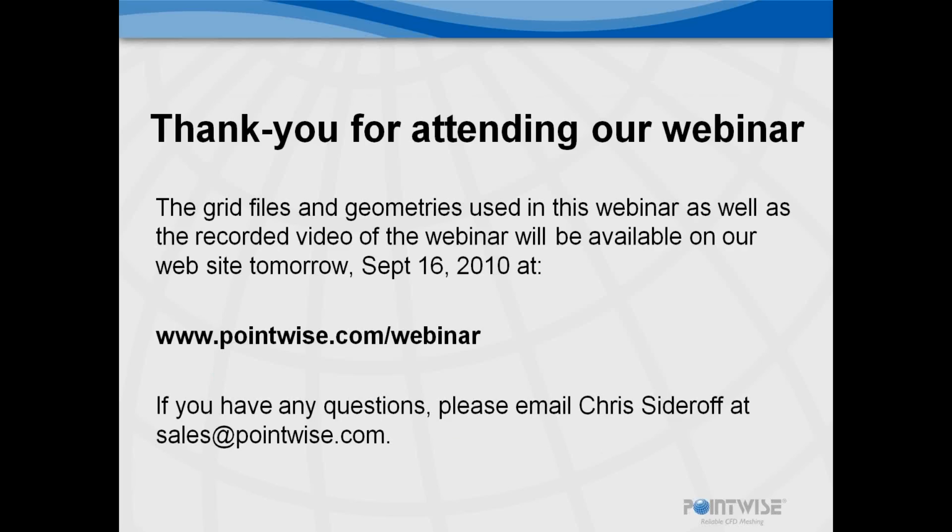As I mentioned, the grids will be available for download tomorrow on our website in a couple of different formats. Just a couple of quick statistics about the grids before I close. The IGV and rotor meshes each have about 800,000 hex cells, and I have the near wall spacing currently set to get a Y plus of about 30. That concludes my demonstration on some of the key techniques I used in Pointwise to create a multi-block structured mesh on the DARPA HIREP pump.